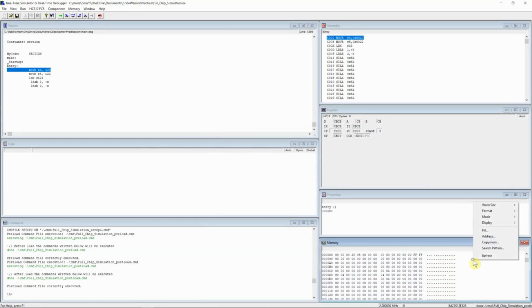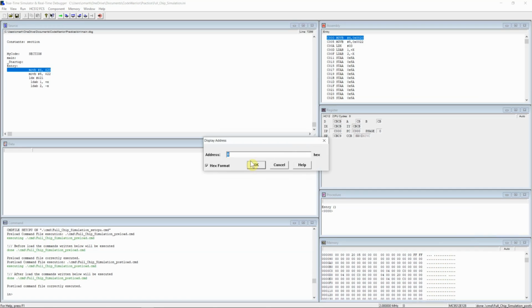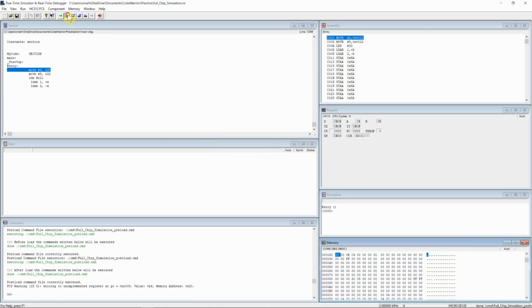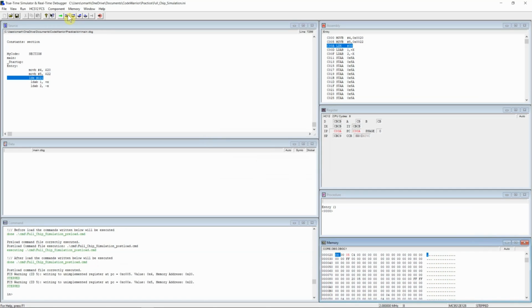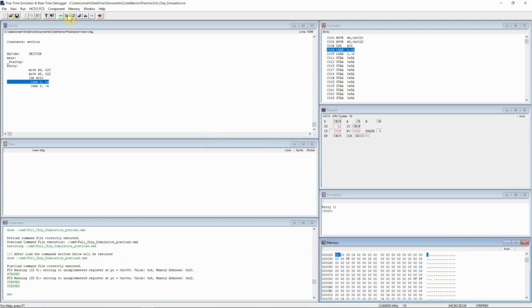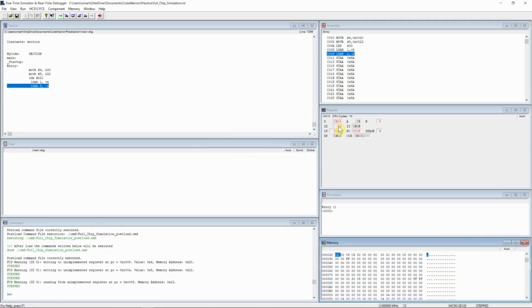Now let's go back to memory. Location 20, 4 and 5 and 20 and 22 respectively. X is 21. Add 1 to x, so that's 22, and then access that memory location, so that's why b is 5. And then subtract 2 from x, 22 is going to become 20. Access that memory location and store that value in accumulator b, so now b is equal to 4.